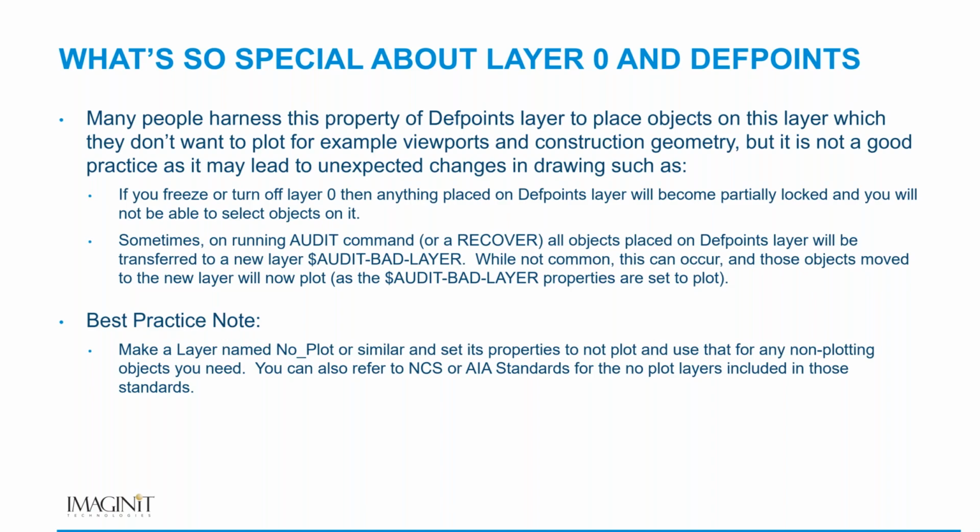Such as, if you freeze or turn off Layer 0, then anything that you have on the Defpoints layer becomes partially locked and you will not be able to select or manipulate the objects on it. That's the big one, and I'll actually demonstrate this.